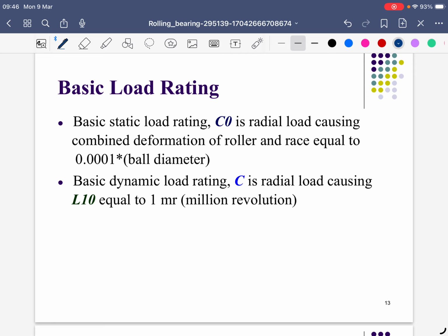Because if you put the turbine, they have the one cross like this, and you put the shaft here, okay? So now your turbine shaft with the turbine is a beam, and the load will go to the bearing all the time.